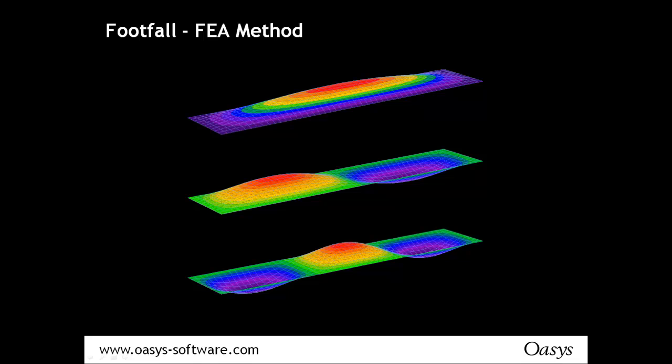But conversely, if you had a floor plate and you took no live load at all, that would be a condition in an empty office building, and who cares if an empty office shakes a bit? It's when there's people in there. So generally the guides say take 10% of the live load for a floor, or alternatively virtually nothing for a staircase or a bridge.